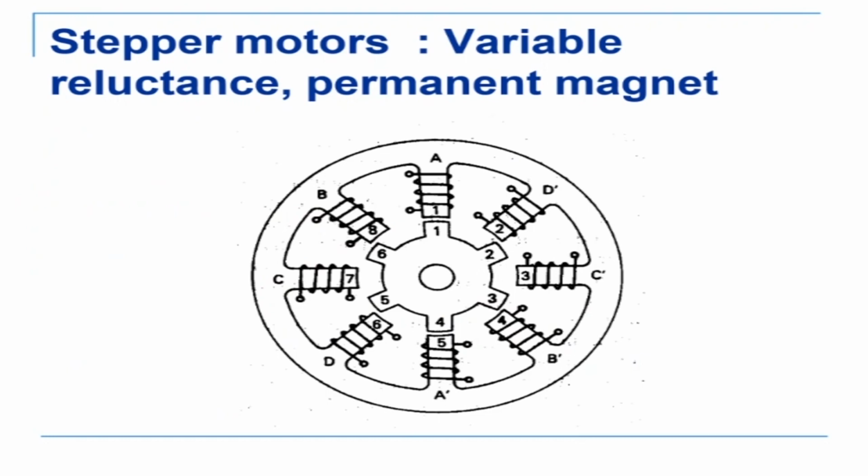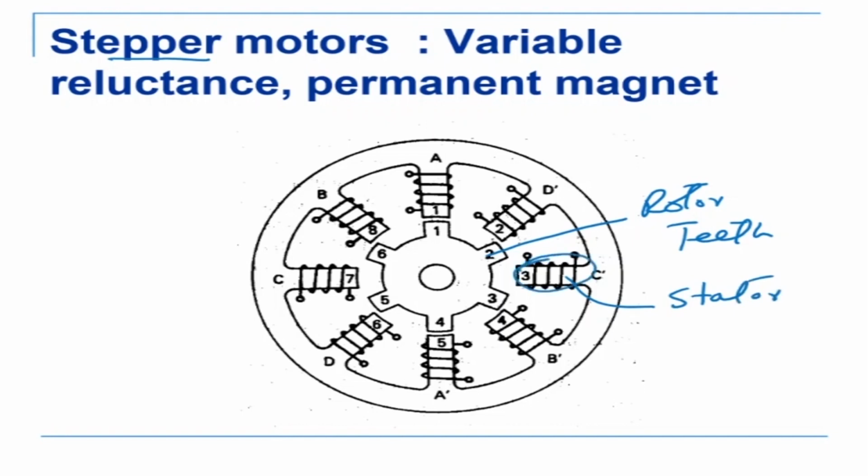I'll very quickly revise. The stepper motor, as the name indicates, moves in steps, and how these motors work is explained by the internal construction. The rotor of the motor has a number of teeth, like 1, 2, 3, 4, they are numbered. And the stator, which is this part, also has coils which are wrapped around the various projections, as shown here. So this is the stator and this is the rotor, and how it works is basically we energize each of the coils in a particular sequence.